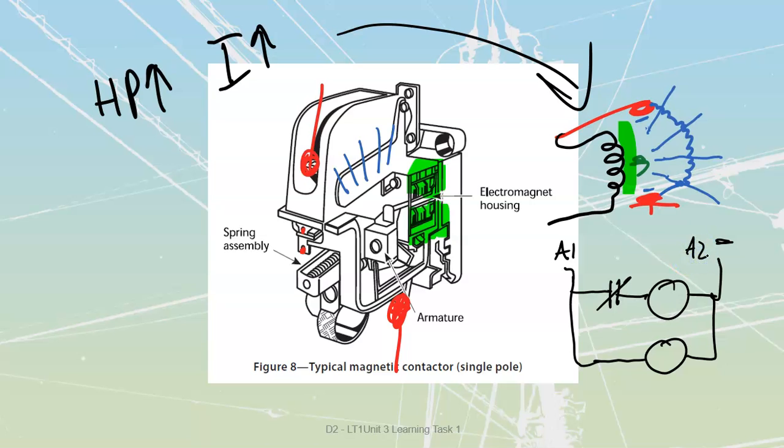Unfortunately, coils, because they have armatures, are going to have the same markings as our DC motors, so we will see A1s and A2s on coils. We'll get past it. You'll be fine. You should be able to identify that this is not a motor. It doesn't look like it does any sort of rotating. Therefore, the A1, A2 off of this is a contactor coil.